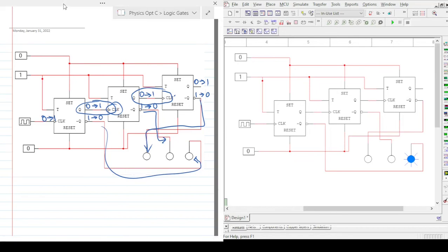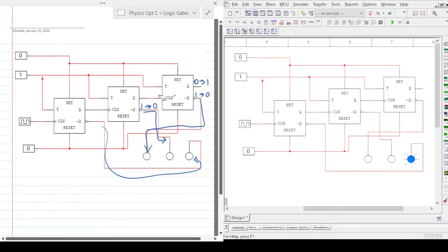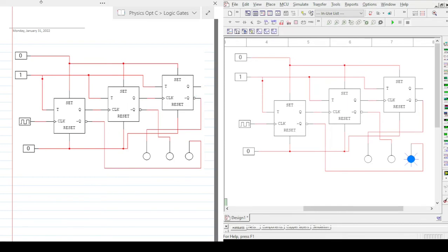So let me clear it up a little bit and then investigate what happens next. So we have it set up here. Remember, the clock is constantly cycling between 0 and 1. So we get to this stage, 0, 0, 0. The clock just had its rising edge, changing everything to zeros, in a way where it ripples throughout the circuit.